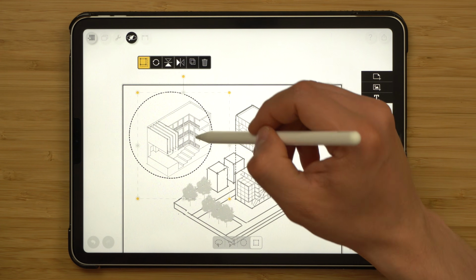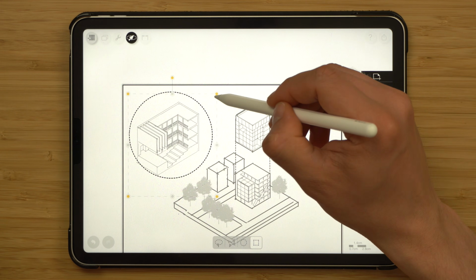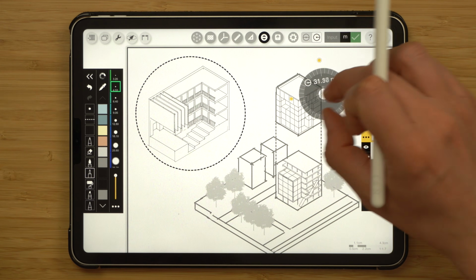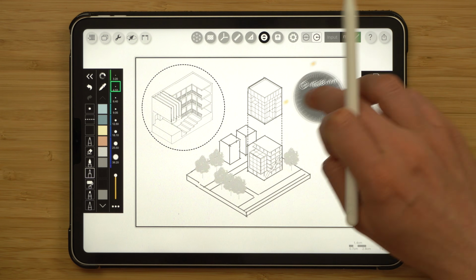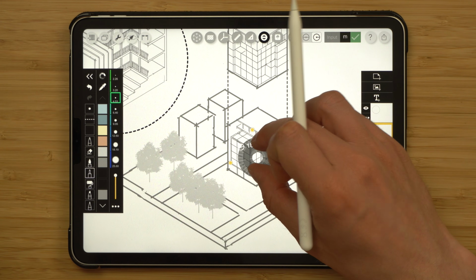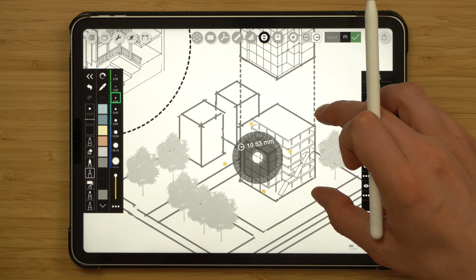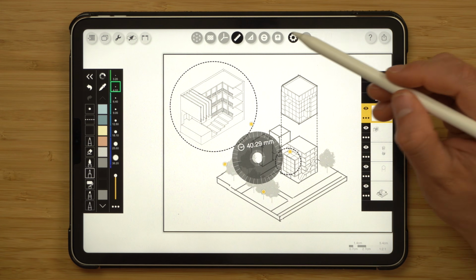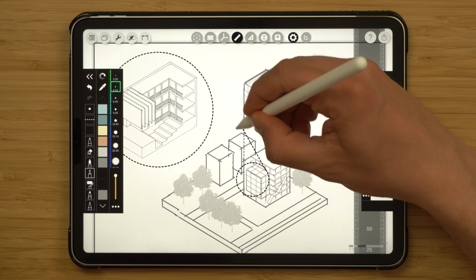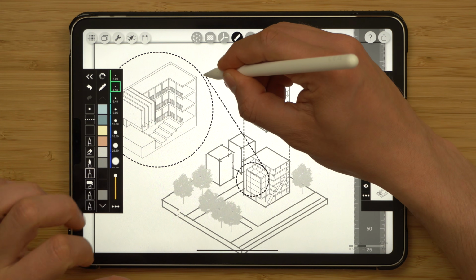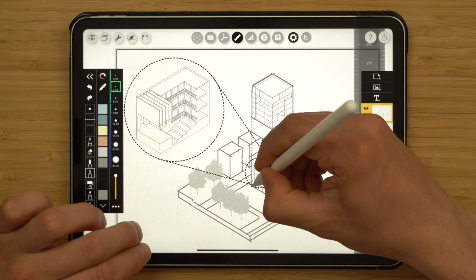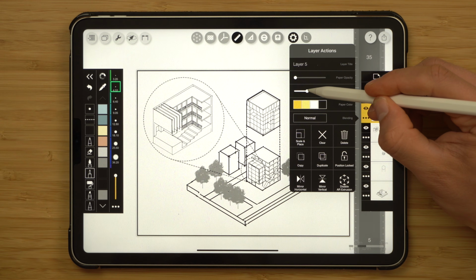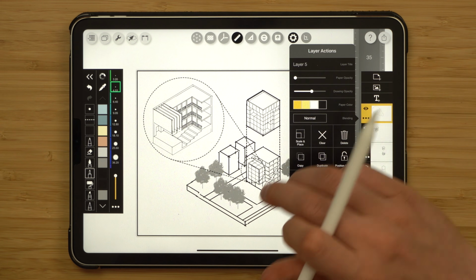So that axle is in line with the circle. Just scale it a little bit, place it within centrally. Activate the protractor tool once more, but this time just zooming into this volume. On the same layer, mark the circle, go back to the ruler and unconstrained line and pull these circles in tangent with one another.